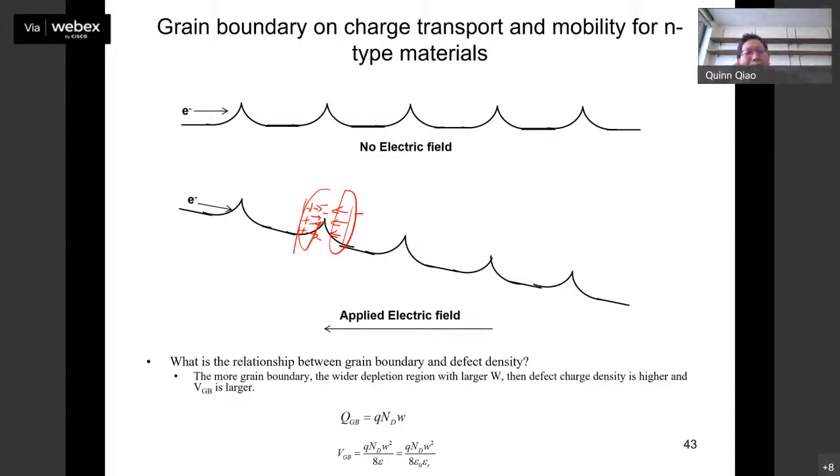Did you get my points? In the depletion regions, you don't have the charge transport. Everything just gets swept over, because the electric field is so strong, just like tunneling, passing through right away. You cannot see this kind of thing. It only happens in the P layer or N layer, outside the junction. Yeah, even in the depletion region, when we are moving perpendicular to the junction, we are finding this type of band profile. Then that's okay.